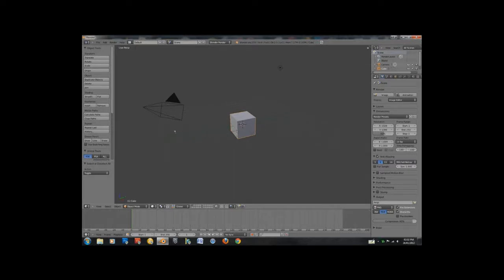We're just gonna hit 1 on the number pad, 5 to get to orthographic. You can see the 1 gets you to the view of the Z and X axes as if you're on the Y axis, and 3 switches to the side view, and obviously 7 to the top. 5 changes it between orthographic and perspective.